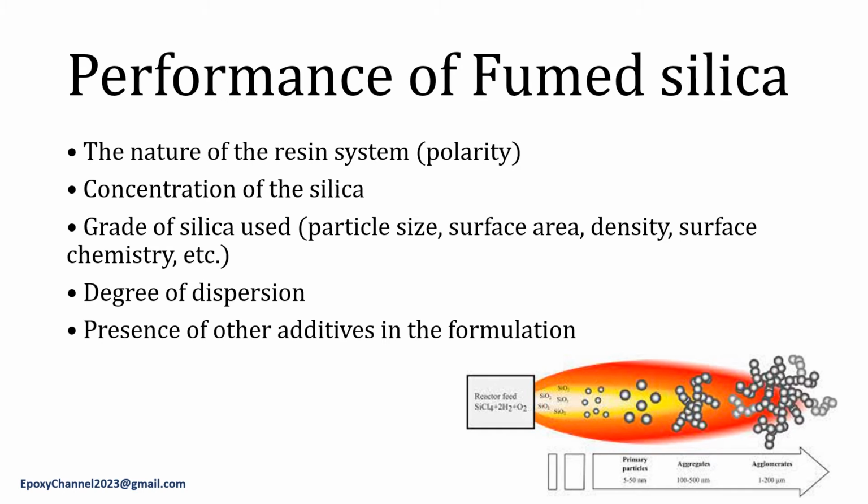Finally, fumed silica is often used in 100% solid liquid resins and results in a surface that is free of texture. The fumed silica also prevents other components from settling, while the extrusibility and spreadability are unaffected. In most liquid epoxy resin systems, fumed silica is only employed at 1 to 3 weight%.